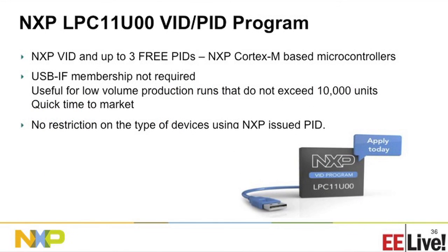So 3 free PIDs, NXP VID. You don't need to be a USB-IF member to get these PIDs, and there's no restriction on the type of devices you design. You can design any devices using the 4 transfer types.